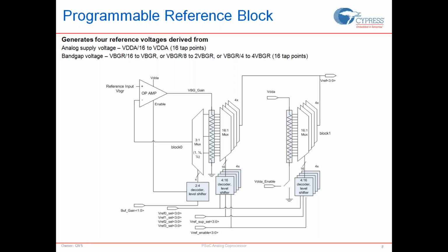There is no way to compensate this unless you actually measure the VDDA, or you use the VDDA as a reference to the ADC itself. Such a measurement scheme is called a ratiometric measurement scheme. So when you want to implement similar ratiometric types of measurement schemes, you would end up using the VDDA as a reference source to your ADC.